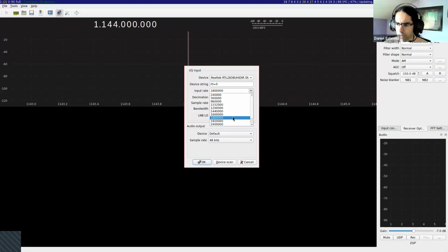So we can choose the sample rate from a list of options. A sample rate which usually works well is 2.4 megasamples per second. We can push it as high as 3.2, but sometimes it doesn't work well. It gives either USB connection issues or it overheats slightly. It can fail, but 2.4 is fine. If you need 3.2 or are interested in checking it out, you can. It's completely safe. You might just hit a problem where data transfer stops running or something like that.